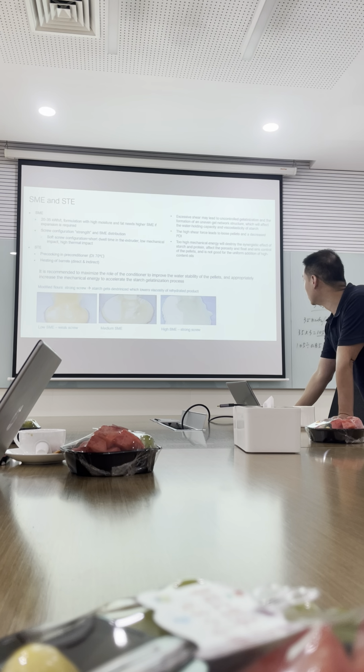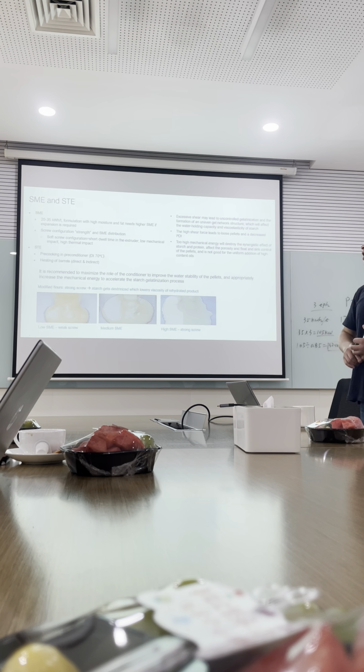And for the SME, I want to highlight one point, because for some recipes, maybe we need quite high SME. We need a very strong shearing force. But that is not good for nutrition, because with too high SME, that means the shearing force is too high, and that is not good for starch gelatinization.